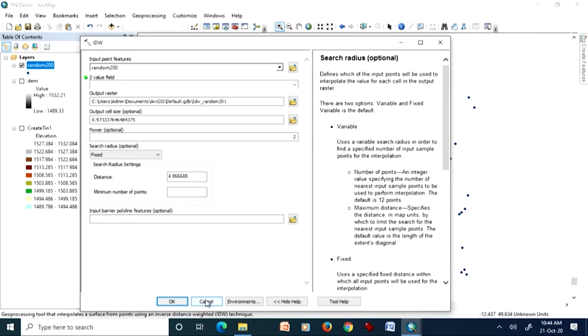Now, using the remaining 10% of points, you can check how close each digital elevation model is. Whichever is closest, you can choose. Once you have found the digital elevation model most suitable for that data set, then you can employ all 100% of the points and generate it.